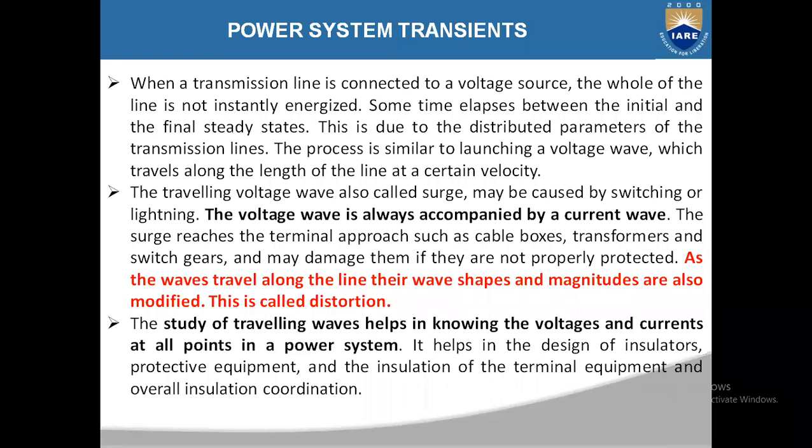In our third module, we discussed short, medium, and long transmission lines. While analyzing the short and medium transmission lines, we considered that the transmission line has lumped parameters, connected either in star or delta. That is, we discussed the equivalent pi model and equivalent star model for a medium transmission line. But that analysis will not be done for this case, traveling wave analysis.